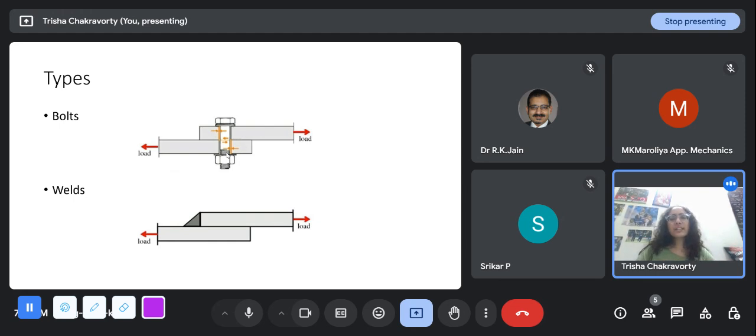Now he asks why, even if we take a normal bolt and tighten it sufficiently, it will clamp the two plates enough to work as a friction type bolt. You are right that that does work, but there is one thing: when you are clamping, what we are basically doing is we're pre-tensioning the bolt. Now, that is why the term friction grip bolt has become synonymous with high strength bolt. Because the bolt has to have a high enough strength to permit that amount of pre-tensioning. If that doesn't happen, the friction will fail.